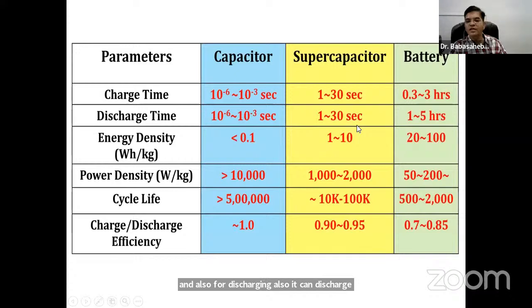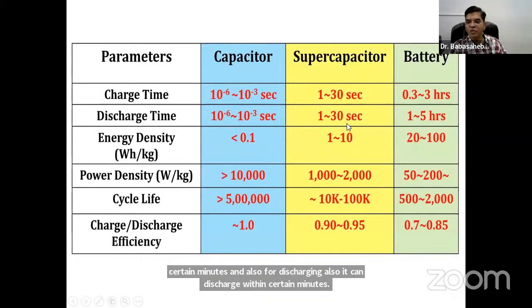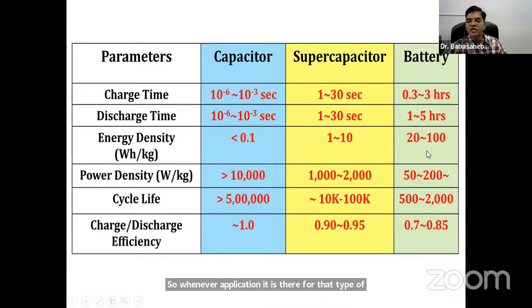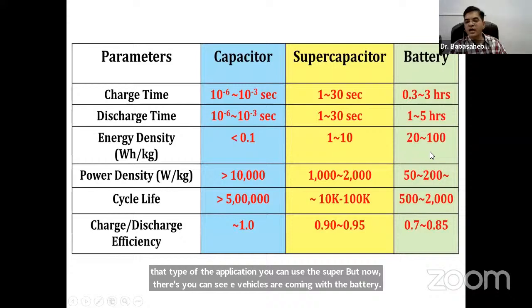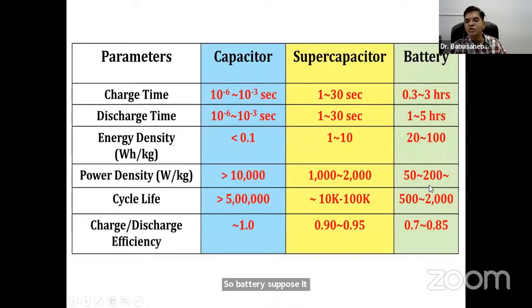So whenever there is an application, for that type of application you can use the supercapacitor. But nowadays you can see e-vehicles are coming with the battery. A battery can have a cycle life of about 2000 to 3000 cycles, but for a supercapacitor it is, for example, 10,000 to maybe 1 lakh.